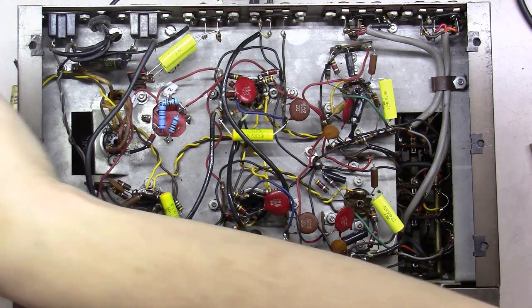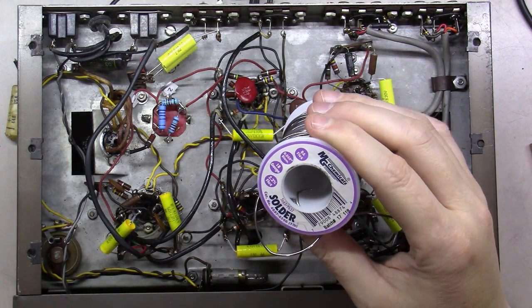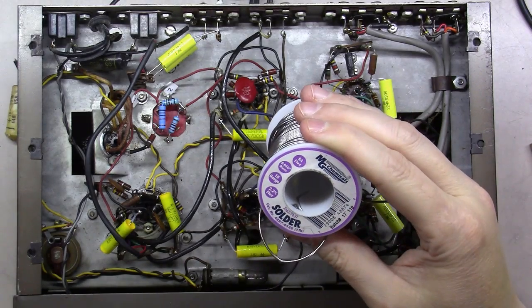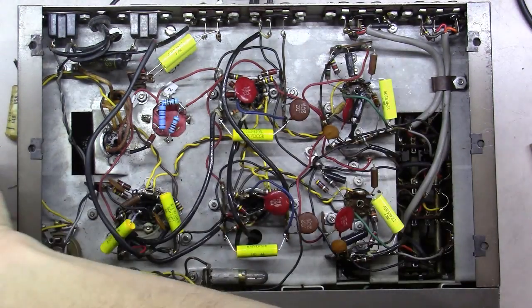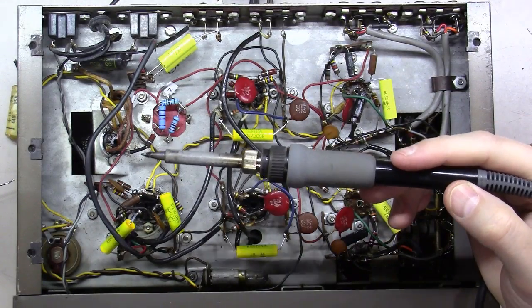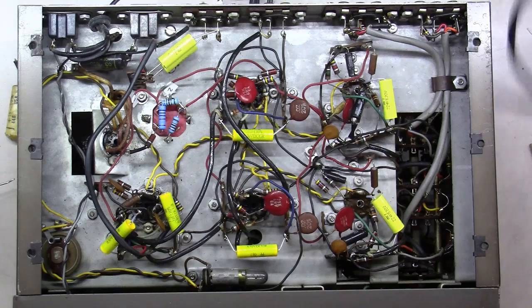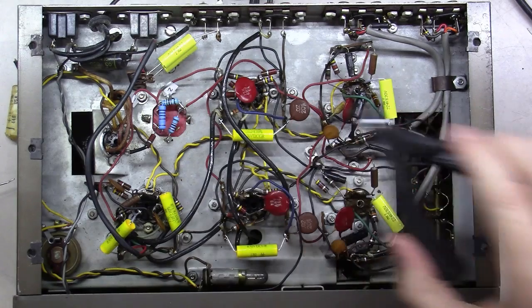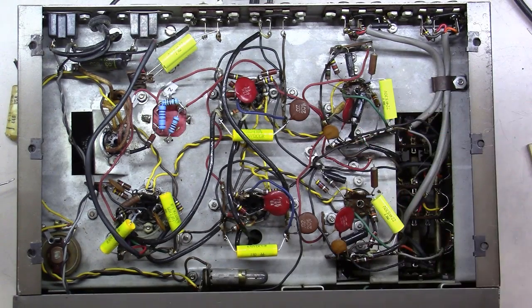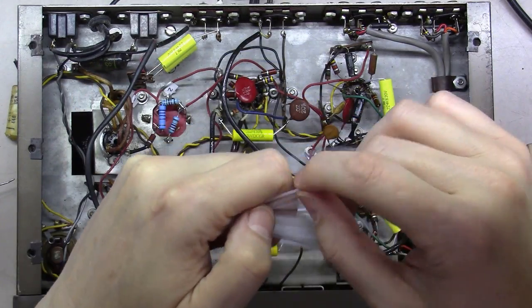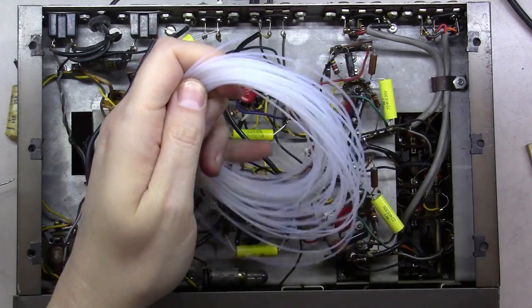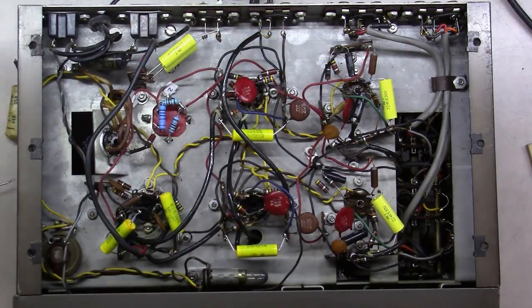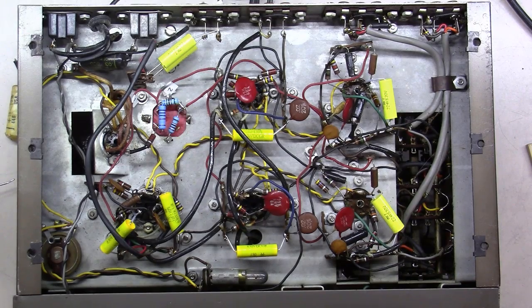Like I say, main thing, I used some 6337 MG Chemicals solder, and in this case it's 0.050 diameter. Just using a Hakko FX888D soldering iron. That's a great little unit for under $100. Normal little wire snip type devices. Some needle nose pliers to help bend some wires with. And then I'm just using some Teflon wire coating, PTFE coating, and I'll put a link down below to where you can pick up some of this stuff.